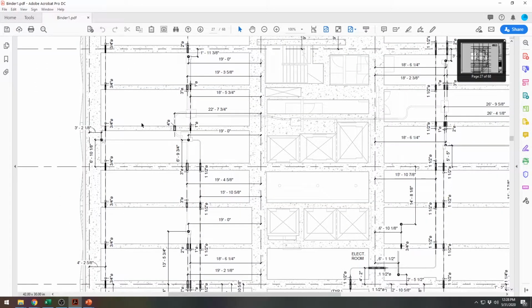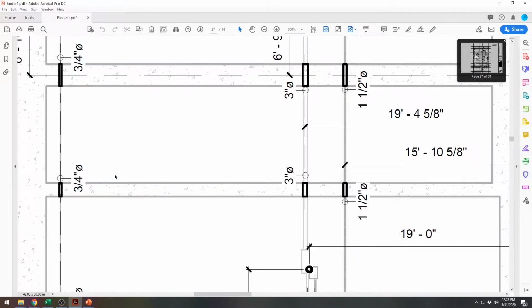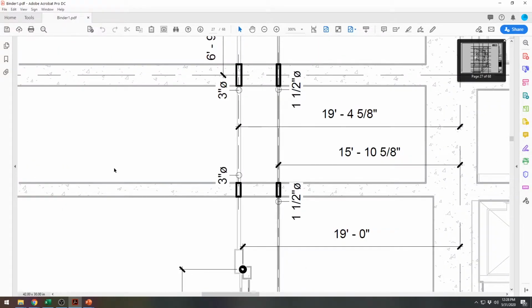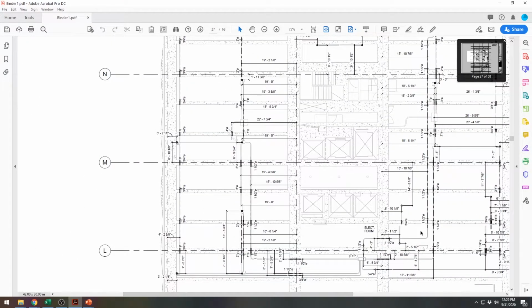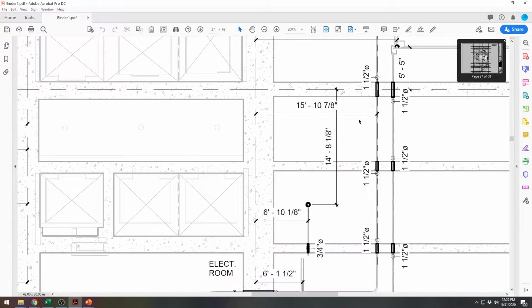Once again, more structural penetrations. It's a lot easier to place as you pour versus drilling it after it's been poured and dried. And this one is actually a dimension plan, from each grid line to show where they had to put these sleeves. And then later it would go back and actually run the conduit.